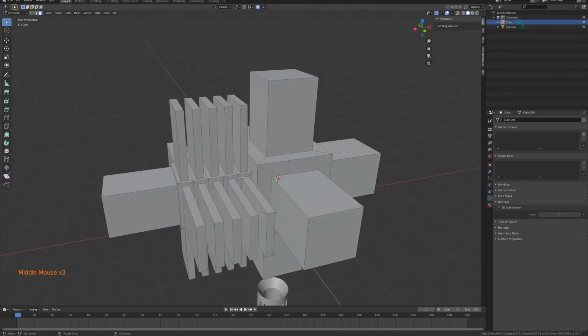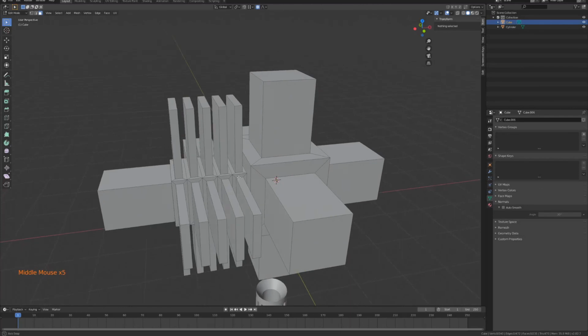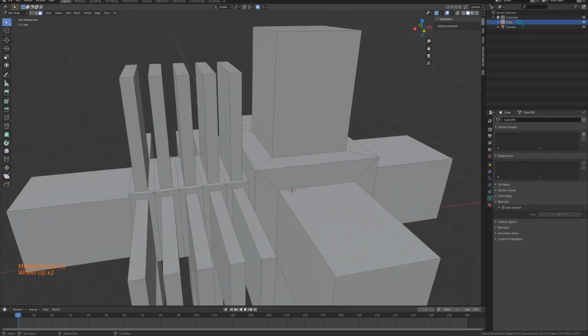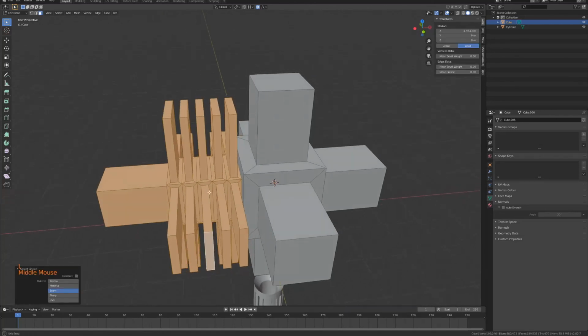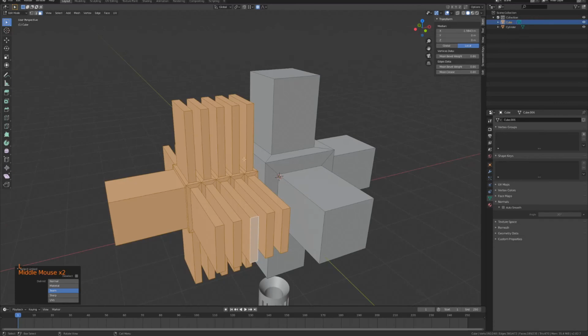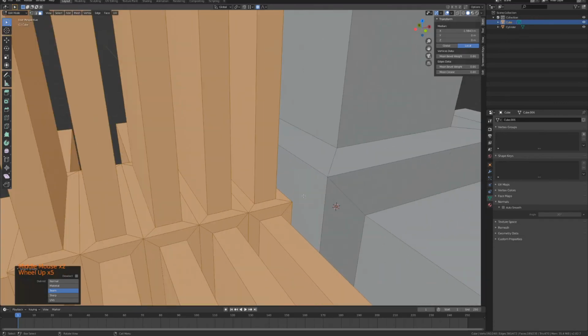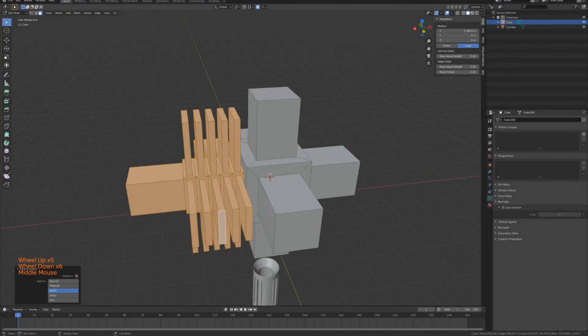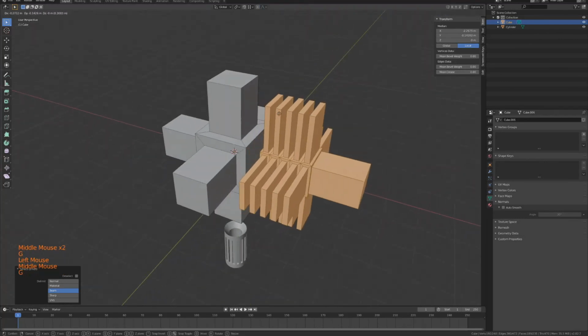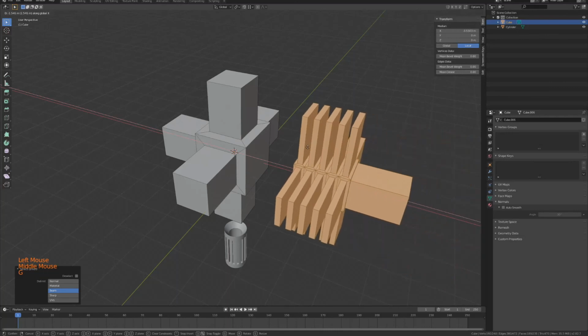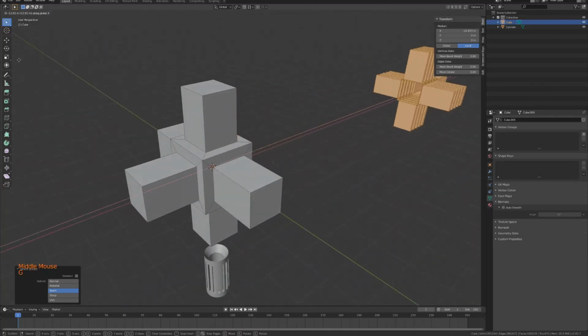It is called Island Select. What Island Select will do is it will go through every single vertice above what you are hovering and select every single vertice that is connected to that. So if I hover my mouse over this shape and I press L, it will select only this because we removed that inset face over here, and because it is no longer actually connected to this part. Sorry, it will select only this part, and now we can move. Oh, apologies, that is something we have not covered yet. And you can make that spaceship fly off into God knows where.